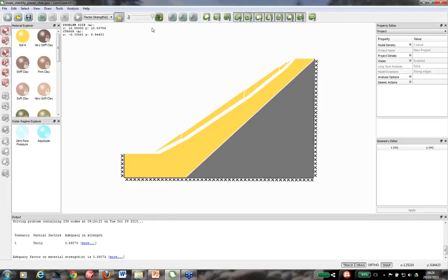And you'll see that in the animation there's a gap forming here. As the soil slides, it's actually modeling dilation, and that's part of the plasticity analysis employed in the software. In plasticity analysis, friction is modeled as dilation. So when you see in these animations for frictional soils these gaps forming, that's perfectly normal. That's part and parcel of plasticity theory.